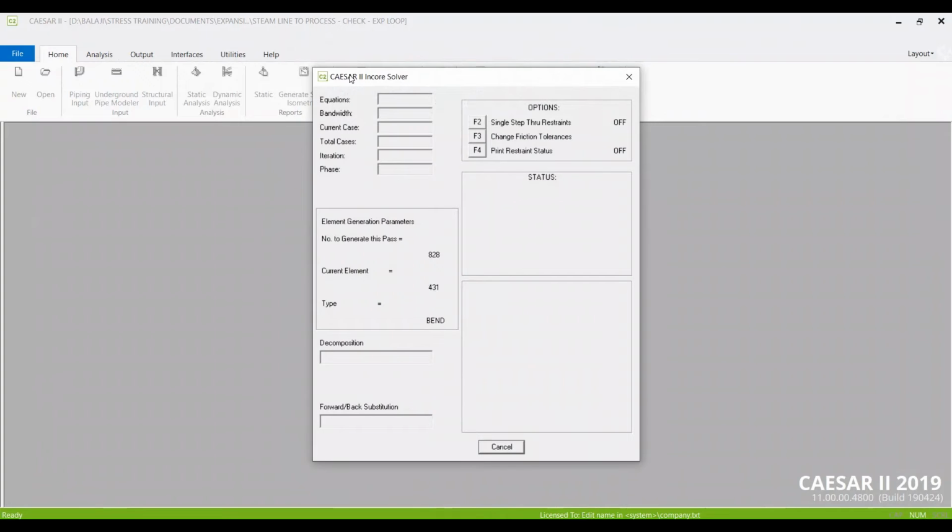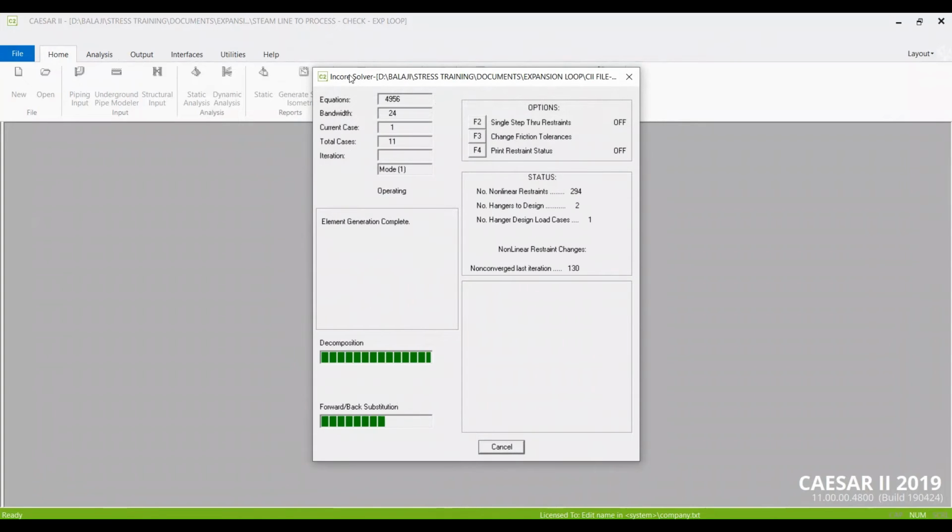So like this, you have to check the displacement for pipe racks or pipes running on the sleepers, for long run pipes and all. We have to add a loop like this only. First, we need to check the overall horizontal displacement at the end point.